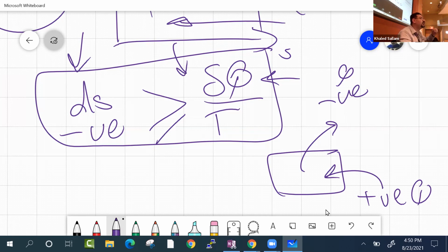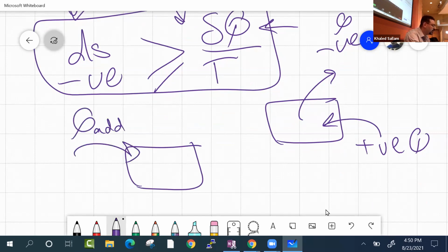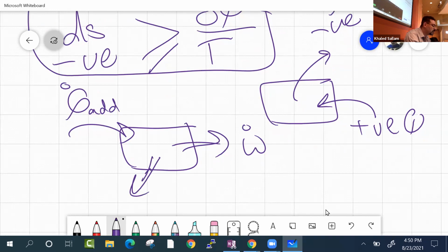You have to have heat rejection so that you can go back again. So when I look at a jet engine or a steam power plant or any control volume, you have to give Q added over here, and you'll get some work, but you always have to reject heat. Otherwise, you will not be able to go into a cycle.